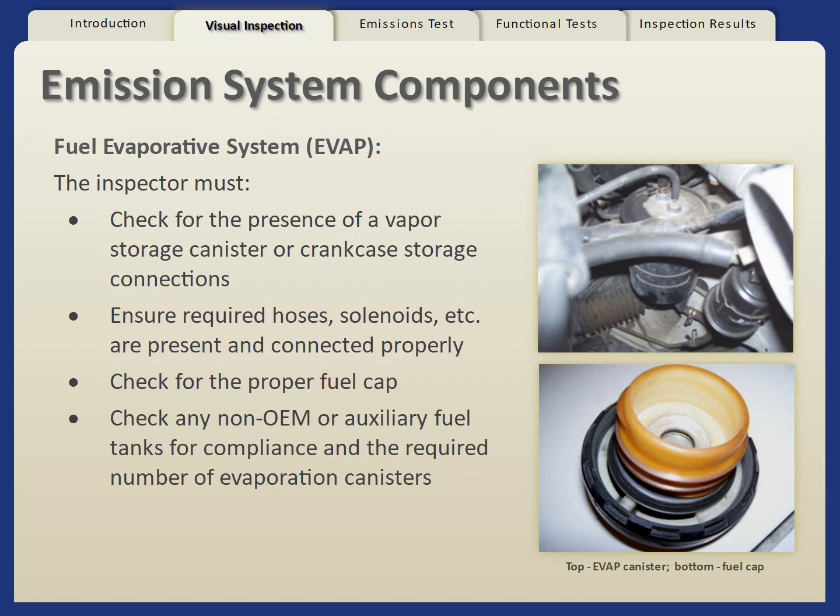are connected properly. It is also necessary to check for the proper fuel tank cap and any non-OEM or auxiliary fuel tanks and associated fuel vapor canisters. Inspectors are not required to perform disassembly of the vehicle to inspect the fuel evaporative system.